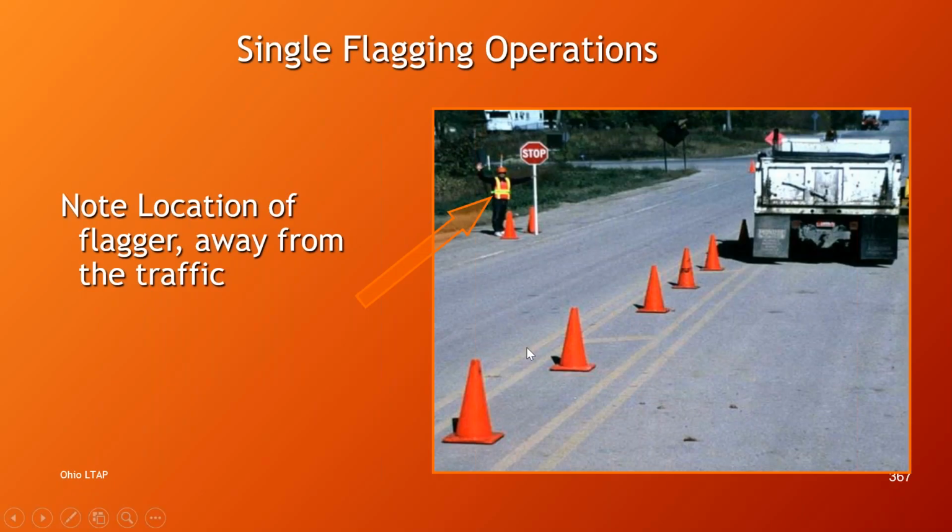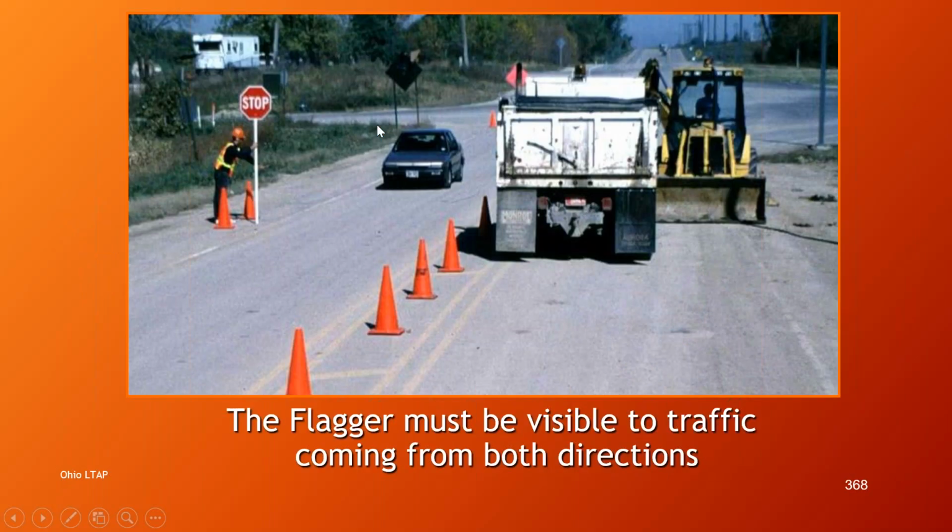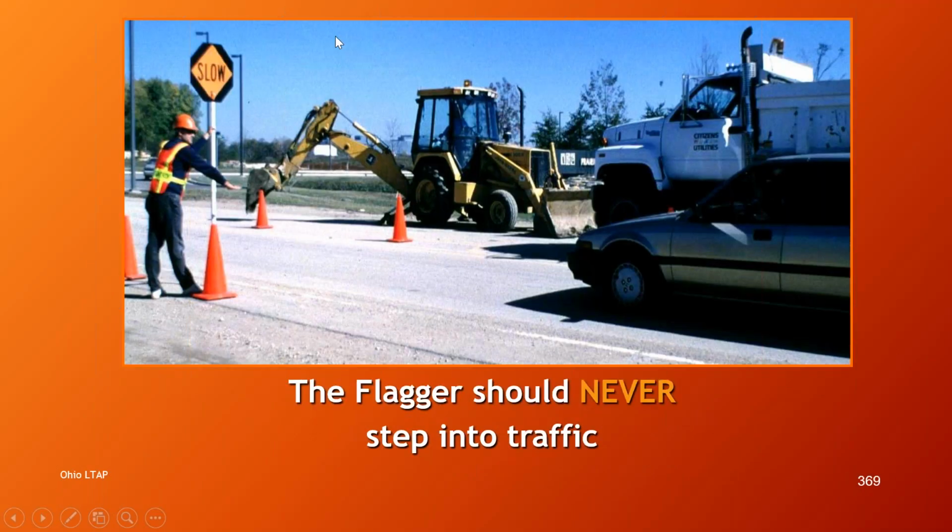So here's a picture of a single flagging operation. You can see he's got some cones at his feet to draw attention to him. And you definitely need to be visible to traffic coming from both directions. And you would never step into traffic. There's no reason why you should step into traffic in this situation.